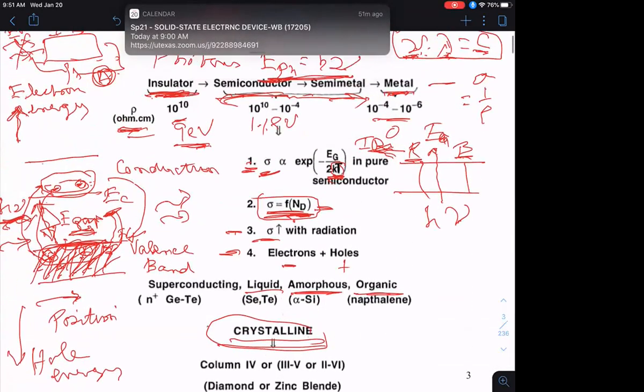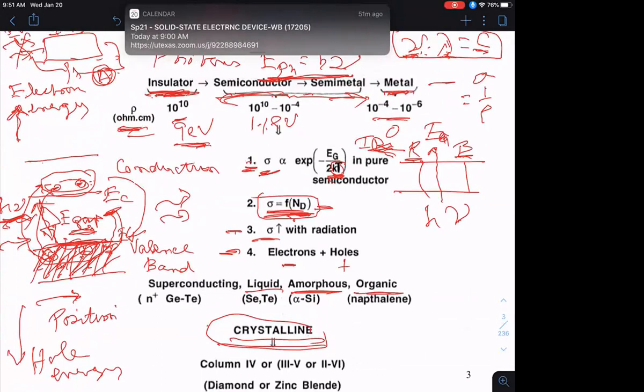What does that correspond to in the band picture? Well, a moment ago, I told you that in a perfect semiconductor, you have these allowed states that are filled up in the valence band. The empty states are mostly empty states in the conduction band, but then the energy gap where you have no allowed energy states for the electron, right? But it turns out that's true only if it's a perfect, pure, defect-free semiconductor. If I intentionally introduce these impurities, then all bets are off. And in the case of this column 5 impurities, which are called donor type impurities, they introduce energy levels close to the conduction band, okay?